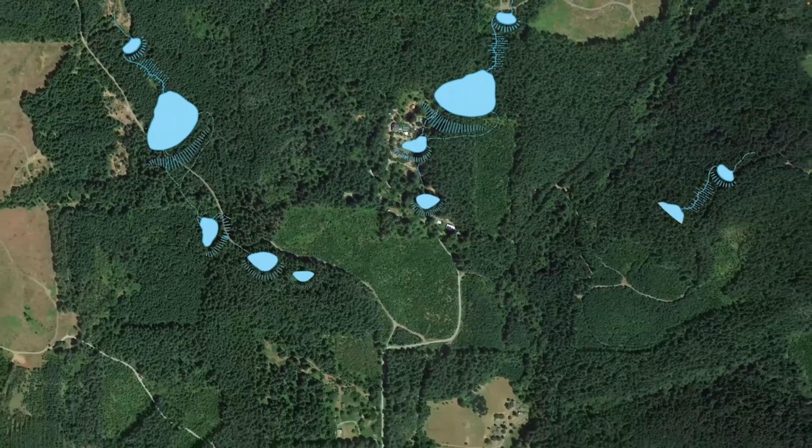The ideal scenario is that from the top of your dam to your water height, you have typically 3 feet for large ponds, and for small ponds, at least 1.5 to 2 feet of freeboard. Freeboard is the term for the distance from the ultimate water height of your pond to the dam top. Now this assures that under no condition will water go over the top of your dam and find a new point to flow over and erode the dam. So the spillway sets the height of your pond water and therefore your freeboard.